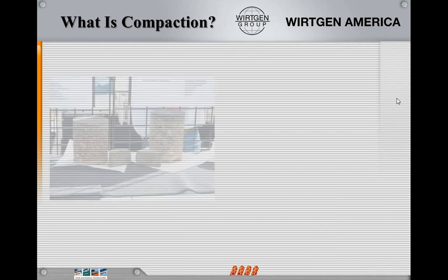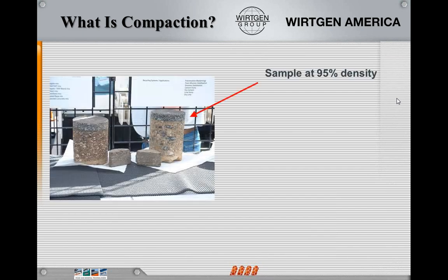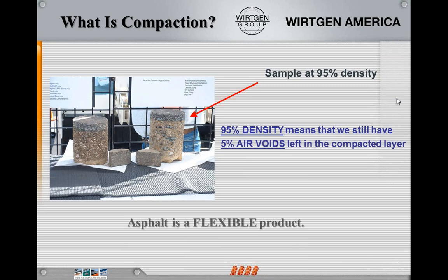On the asphalt side, we are not going to get to 100%. We want to have some kind of air void content in there. Typically, most mix designs are designed around 4% voids unless you get into like an SMA or an open graded friction course mix. But most of the time, we're around 4% is where we design the mixes. And that's usually after about a 7-year lifespan, we anticipate that mix to be down to about 4% voids.